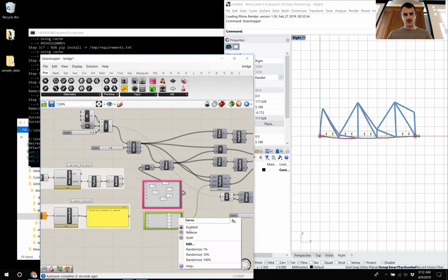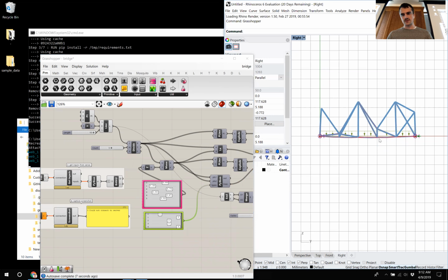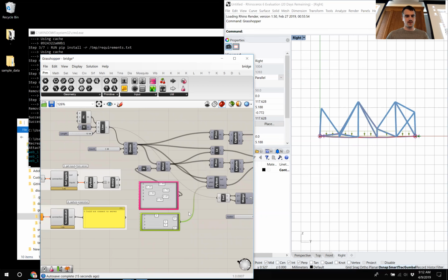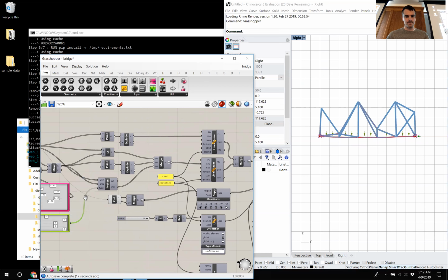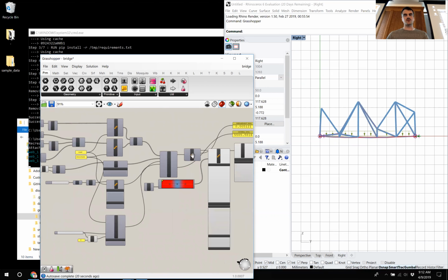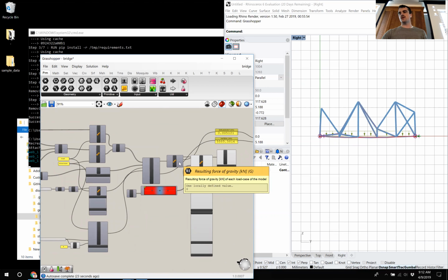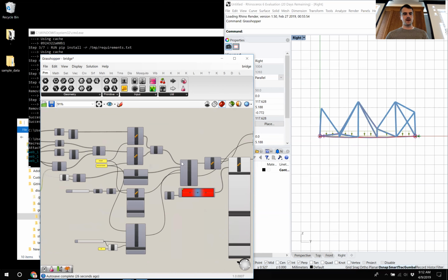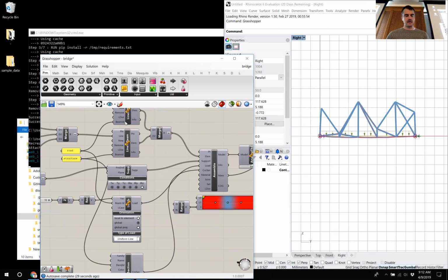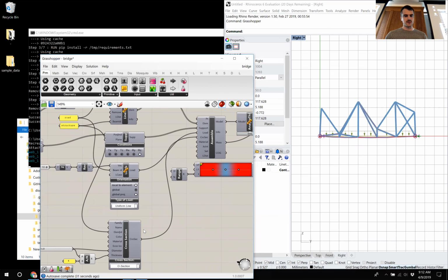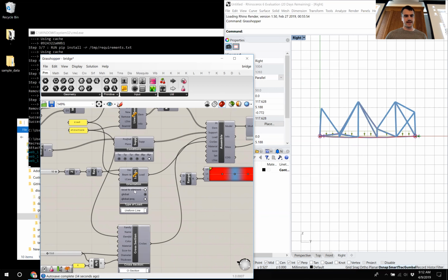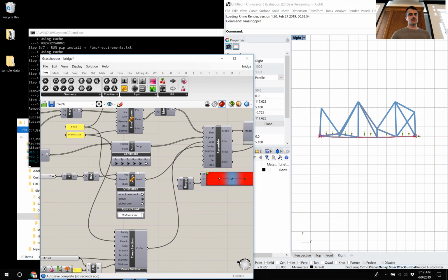So you see more structure appearing. And now if we shuffle this, you'll see the different structural types. There's 2 types of diagonal bars, nothing, and then X cross brace. Okay, so that's our model. And then it gets put through the structural analysis, which you can look at on Medium for more details about that. It's a pretty basic structural analysis, just converting lines to beams, giving them a basic cross-section here, and then applying a set of loads and constraints or supports for the model.